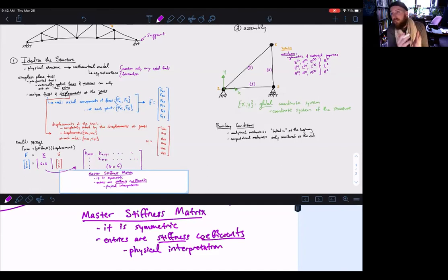These are the things that typically come out when you multiply all of the components of the strain energy: things like the modulus, the second moment of area, I, and the length. And then you can imagine this for any physics that you can cook up, all of the resistance to deformation is going to go inside this stiffness matrix. How stiff is this structure to the various types of displacements being applied?